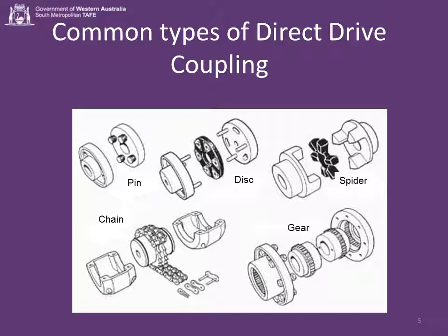Misalignments are inevitable due to small differences in tolerance and load-induced or thermally induced movement due to support, the weight, or bending under load. Misalignment is allowed for by connecting the shafts using a shaft coupling.